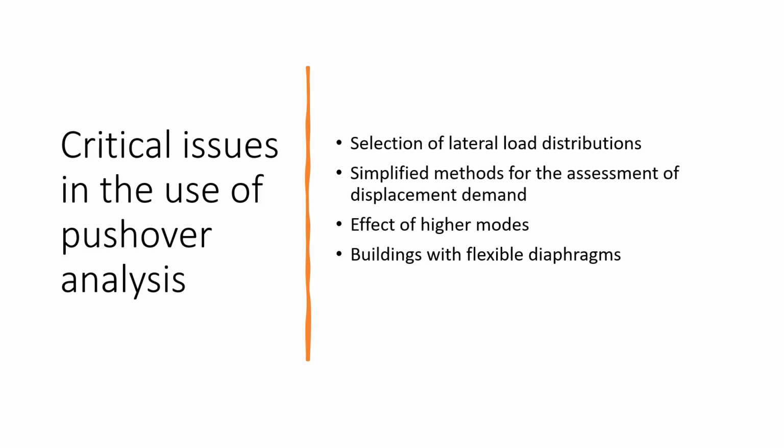The engineer is then requested to provide an intervention that cannot be fully specific for a single record or a single analysis, but is requested to strengthen many and different piers, for instance, in a masonry building, that possibly are not necessarily those involved in the real failure mechanism.